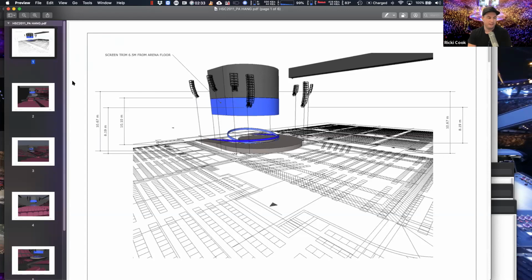Good. I love the chain motor bags. When the chain motor bags go and hang right in front of your HF on your array, and they go, oh, it'll just go around it, right? And you're like, well, it's this much, and by the time it gets to the back of the room, it's this much. But what happens is it's this much close to the PA. So you're going to put an object that's this wide in front of it, and therefore there's nothing going out the front.